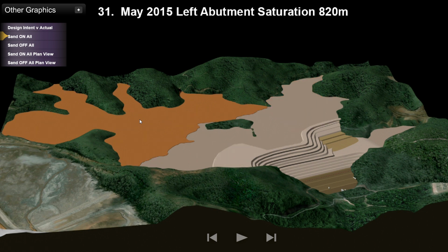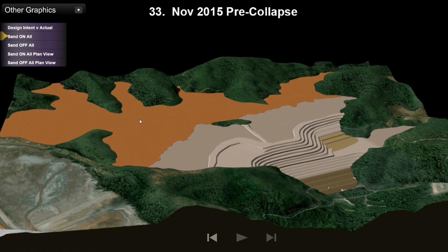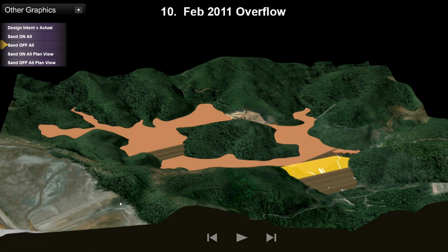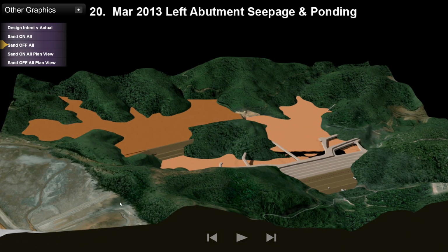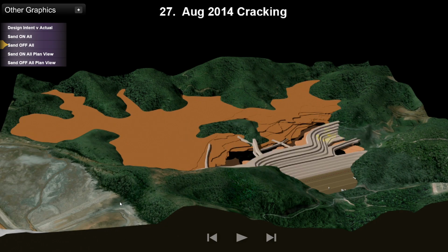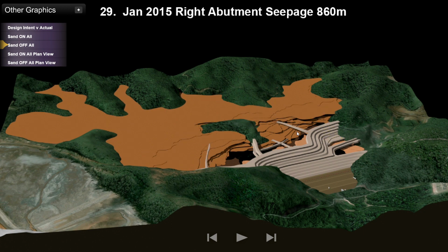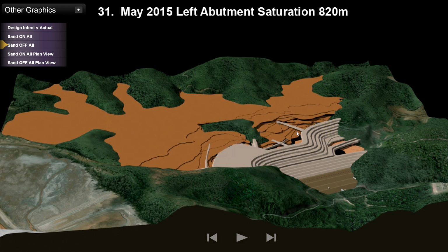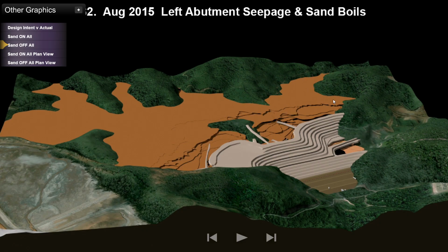The problem with this was that they ended up with a structure that wouldn't drain, and our special contribution to this was to illustrate the structure of the dam without the sand getting in the way. So that what you can see back here is every day that they added slime that wasn't supposed to be down in this area, you can see a buildup of those layers. So they had slime stacked on top of sand, which was stacked on top of slime, and these structures wouldn't drain.